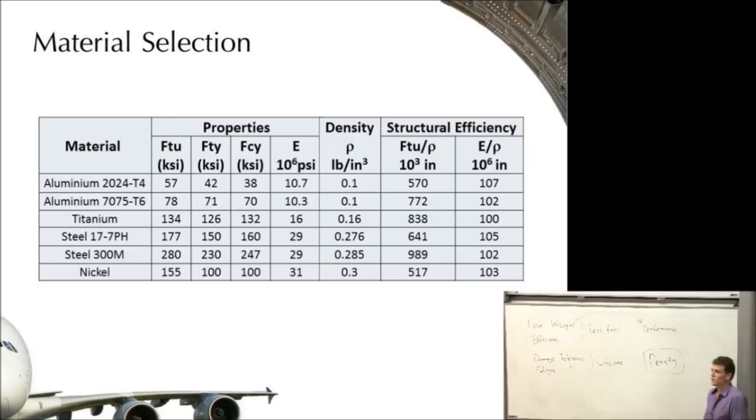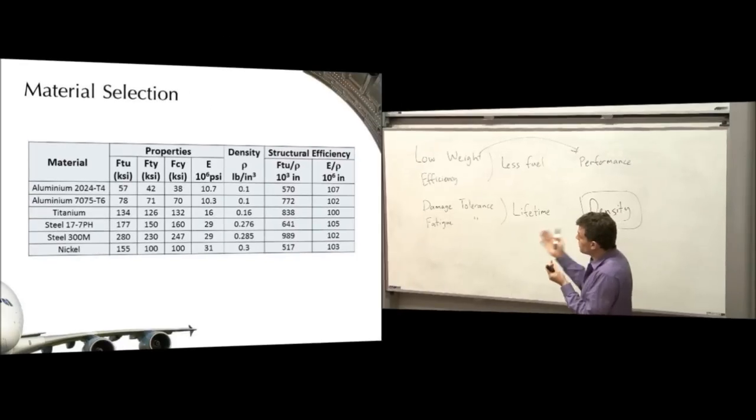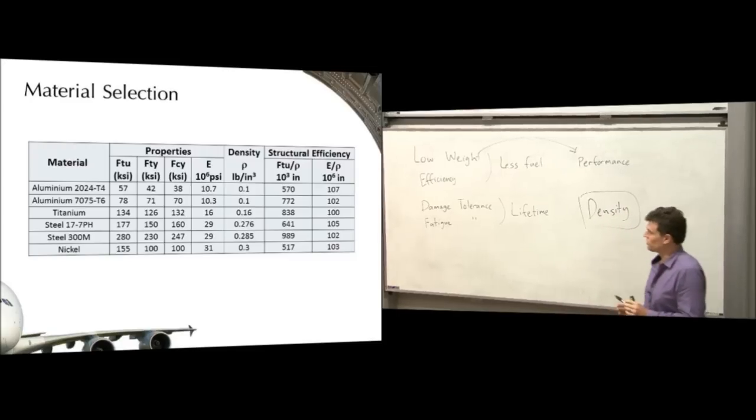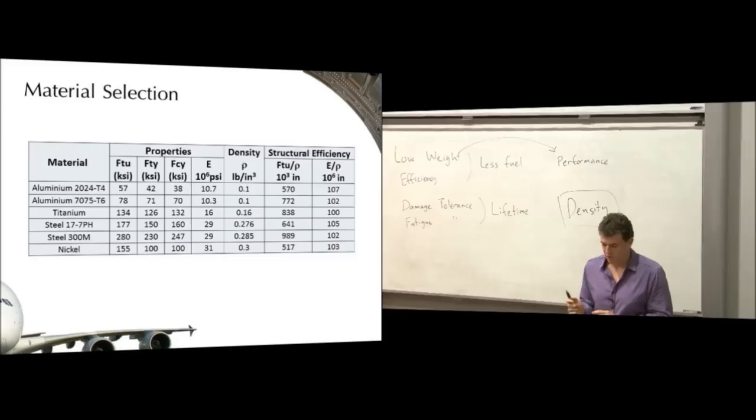So when you say steel is too heavy, well, even when you divide by the density, steel is still stronger. If you wanted to do a weight-for-weight comparison where you had the same strength piece of material, the steel one would be lighter than the aluminium one. So the argument about density is partially true, as we'll see in a minute, but it's not completely true.